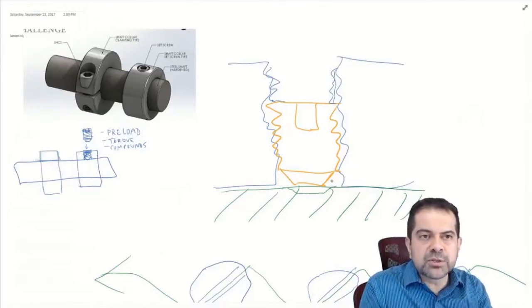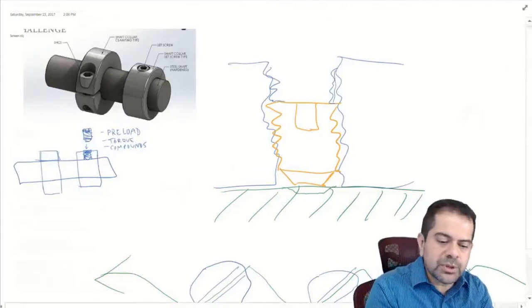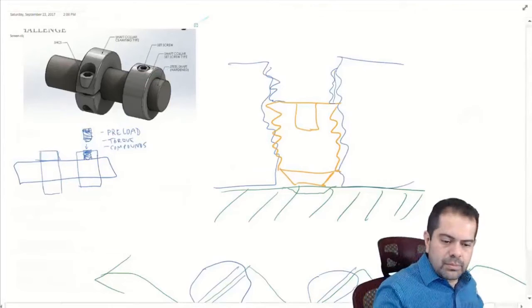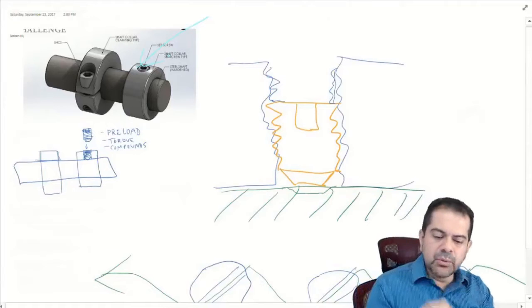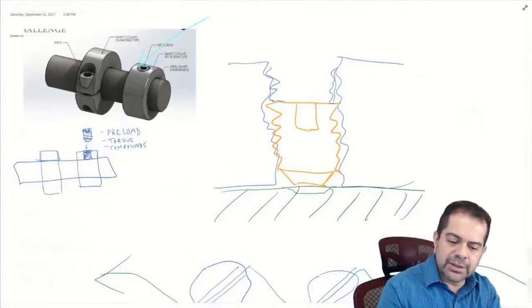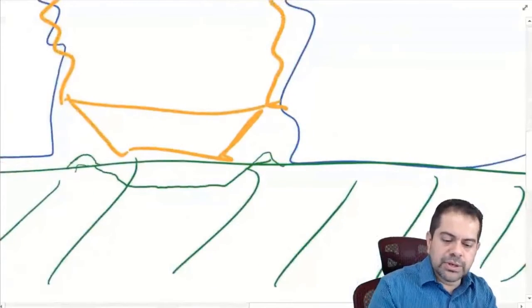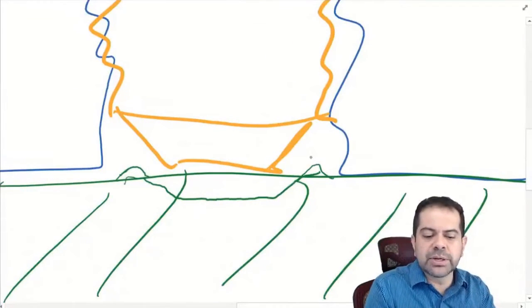The user has to be able to easily remove and reinstall this collar. We're talking about this guy over here. This approach here. When you deform the metal like that, not only does it indent downward, but usually the material looks for somewhere to go. So it'll also create a little ridge or a little mountain all the way around.